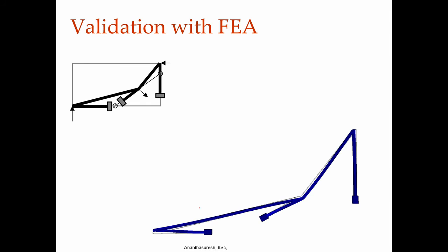So this is what we just designed graphically and you can see how this moves. This point is moving that way, this moving that way just like this arrow shows, and this point is moving that way. So you got a compliant mechanism in 2 minutes, right. Even though it is a non-intuitive specification, when you move here, how does it go? You can get that. So you can watch this for a while and study this method to understand.